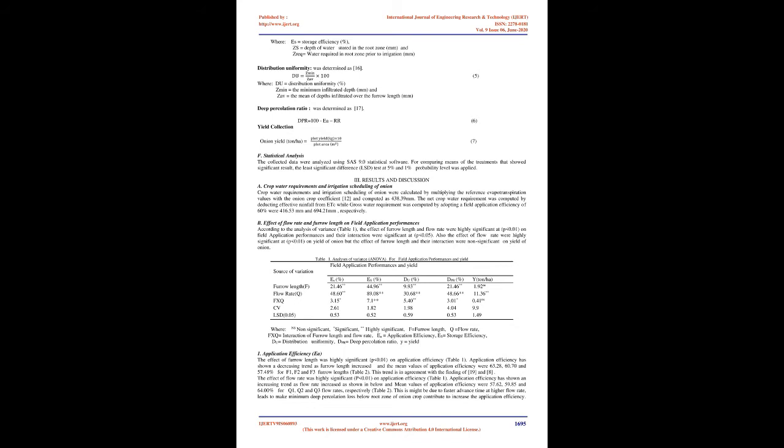13. D. Soil sample collection and analysis methods. The disturbed and undisturbed composite soil samples before planting were collected at depths of 0 to 20, 20 to 40 and 40 to 60 cm. Bulk density, soil texture, pH, electrical conductivity, field capacity, and permanent wilting point were determined by the core sampler method, pipette method, pH meter, electroconductivity meter, and pressure plate apparatus by applying a suction of 1/3 and 15 bars to a saturated soil sample, respectively.